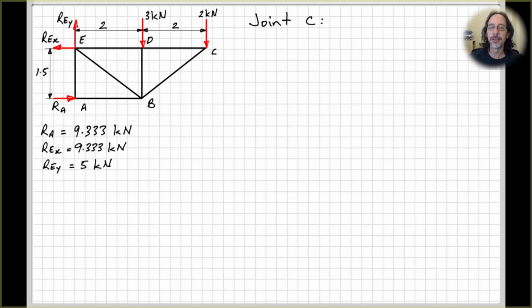All right, so remember, in using method of joints, we're looking at particle equilibrium for the joint. And if it's particle equilibrium, then we only have 2 equations of equilibrium that we can use. So therefore, the maximum number of unknowns that we can solve for is 2. When we go to look at other joints, such as D and B, we need to use the values that we found at joint C in the free body diagrams of joints D and B, so that then we can find the values of the other unknowns.